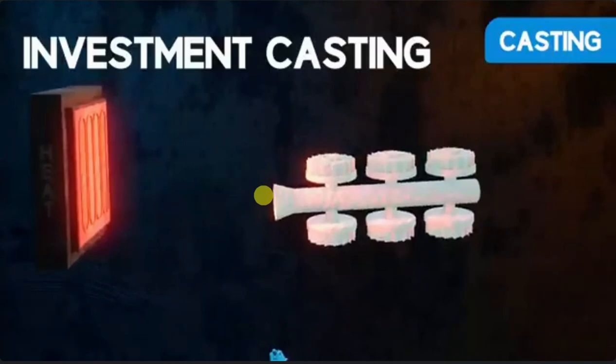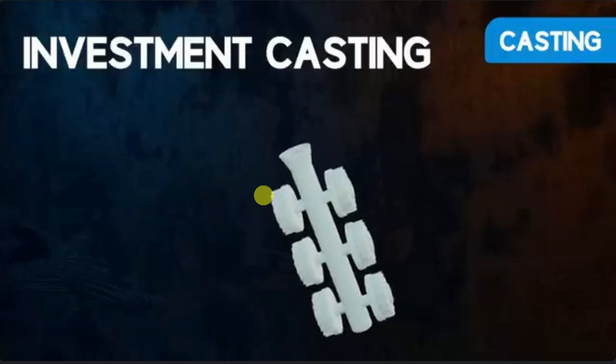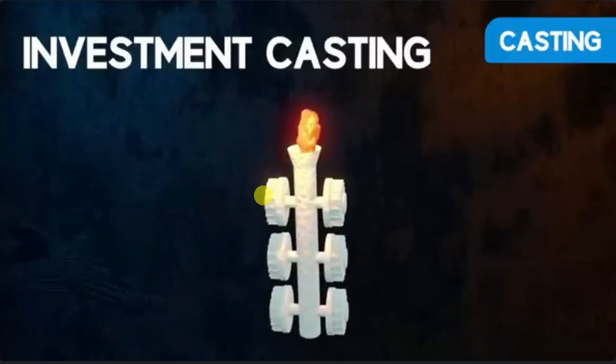So the basic thing in investment casting is that they prepare the pattern using wax, then immerse it in a ceramic slurry. Then they expose it to heat, and obviously the wax will melt, and finally you get the shape of the final product. So the ceramic mold is ready now.